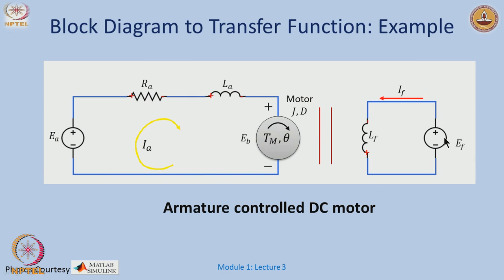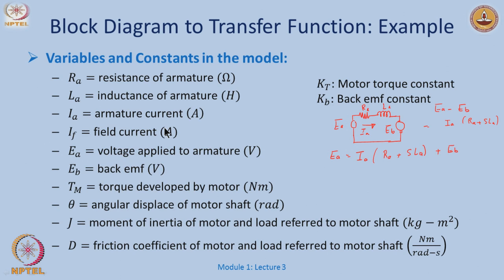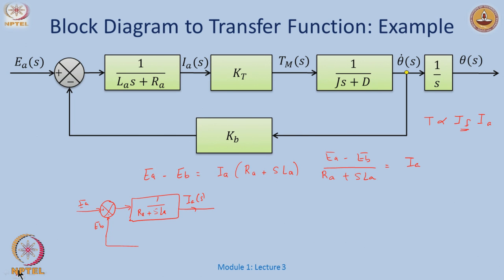Therefore, what is variable here is just the armature current. As the load varies, the armature current would vary, and therefore, the torque I can rewrite as T is some torque constant times the armature current. Okay. So, I will have Kt and the Tm here.